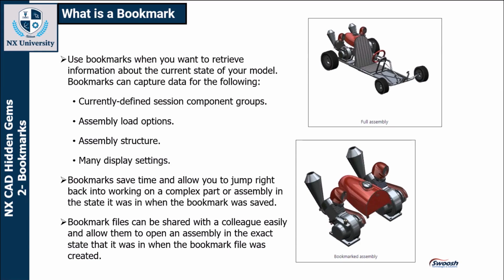So if I'm working on a project and I have certain components hidden in the display, I have that zoomed up on in a sublevel assembly I'm currently working on, and I want to share that with a colleague, I can save a bookmark, send that bookmark file off to the colleague. They can open up that bookmark file. NX session will open up. It's going to load all of the components as they were saved. That is the components that were currently displayed on the screen, the level of zoom on those components, as well as any graphical display of those components will be retrieved from the bookmark and will open up on that user session, and they'll be in the exact same position that I was viewing the assembly when I saved that bookmark.